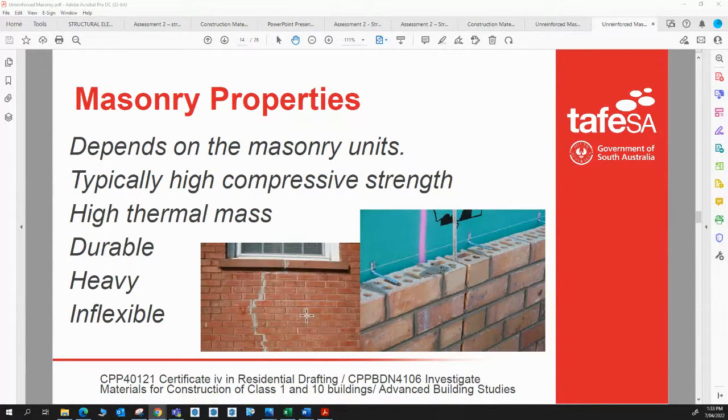So what happens is when you get flexing in that structure, it simply starts snapping through the brickwork. And that sort of snapping is, to my eye, possibly a little bit more concerning than the stepped cracking. The stepped cracking is something you see a lot, where you get this stepped cracking along the mortar work, emanating from a corner of a penetration. That's a fairly normal thing to happen.